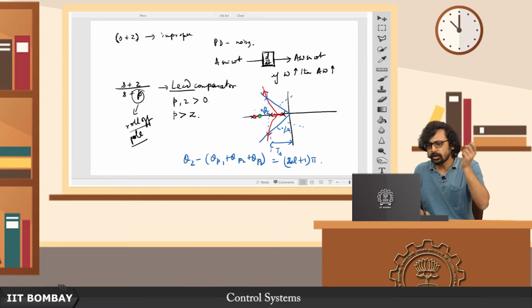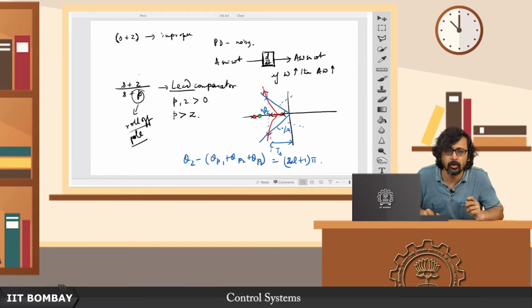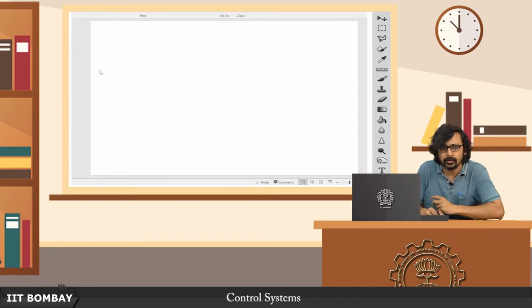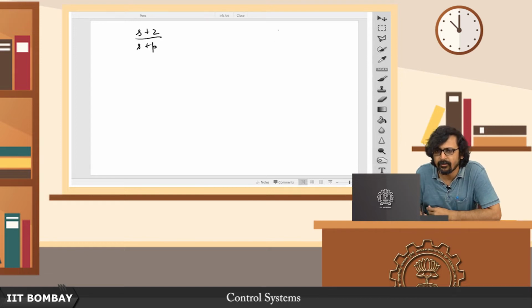Yeah. Now the question is, can we not do this using a pole 0 pair instead? Of course we can. How so? Now consider this s plus z upon s plus p. What effect does this have on a point on the complex plane? Suppose this is our desired closed loop pole, minus pc1 and minus pc2.